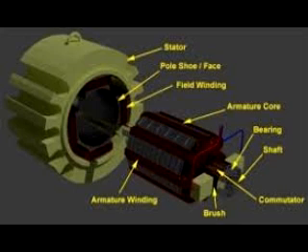The current in the field coil and in the rotor are independent of one another. As a result, these motors have excellent speed control characteristics. Shunt wound brush DC motors are typically used in applications that require 5 or more HP, such as industrial and automotive applications. As compared to the permanent magnet brush DC motors, shunt wound brush DC motors have no loss of magnetism and are more robust.